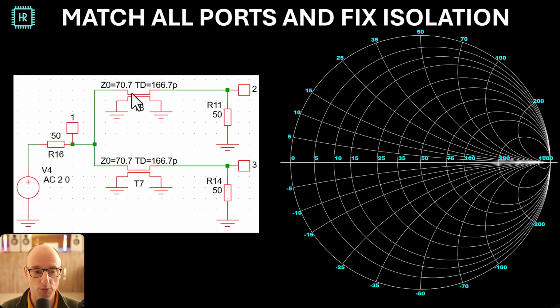That gets transformed by this transformer. Now this transformer rotates from 50 to 100, so the center point is here. If we start at 33, the circle will become much larger. Actually, we're going this way. And we would end up at 150 ohms. So 33 quarter wave transforms to something like 150. So we would see 150 ohms looking in here. Another thing is that we have 3 dB loss in this direction and 3 dB loss in this direction, so our isolation is only 6 decibels.